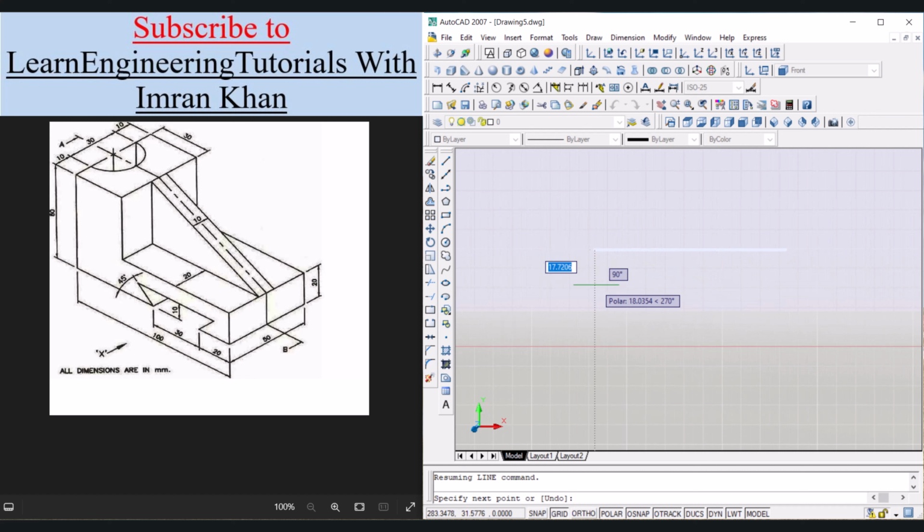Now in the negative y-axis we will go with 20 mm thickness. In the positive x-axis we will give the value of 50. Enter. We will also give the value of 30. Enter. And then 20. Enter. And we will try to close this object, so write C. Enter. Now the 30 mm thickness line should be removed. Press delete.